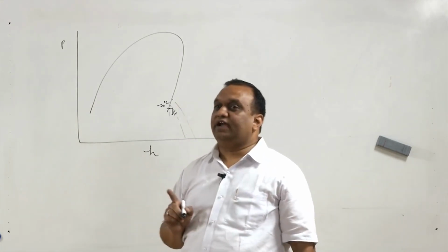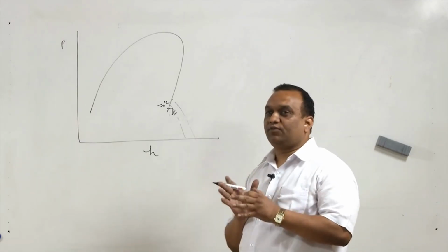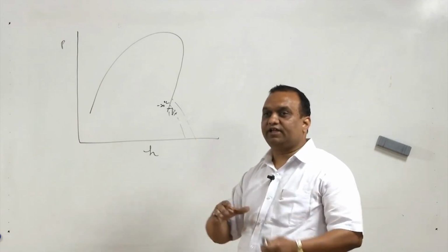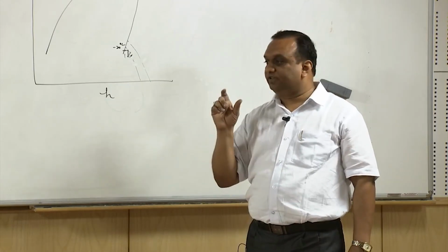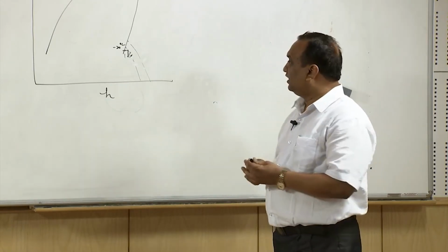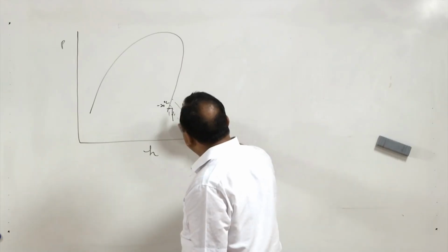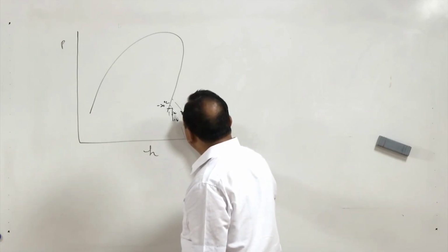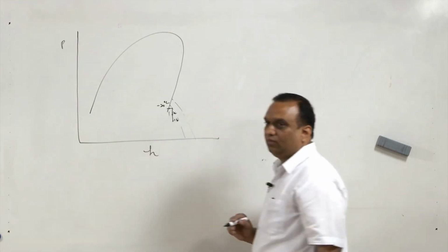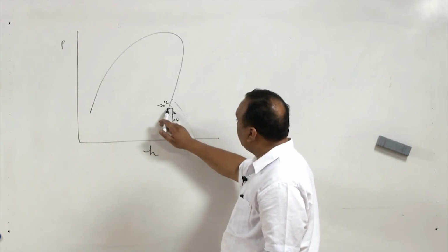Further, when the vapor is entering the compressor, there is a pressure drop across the compressor wall, because the pressure in the pipeline is higher than the pressure inside the compressor. So, this pressure drop takes place across the compressor wall, and we get state 1B. I am repeating here that the vapor coming from the evaporator is saturated.